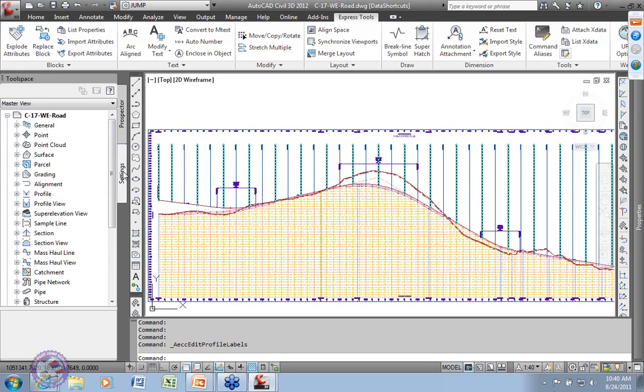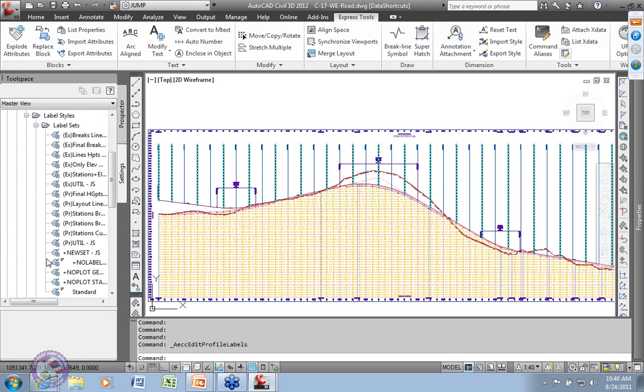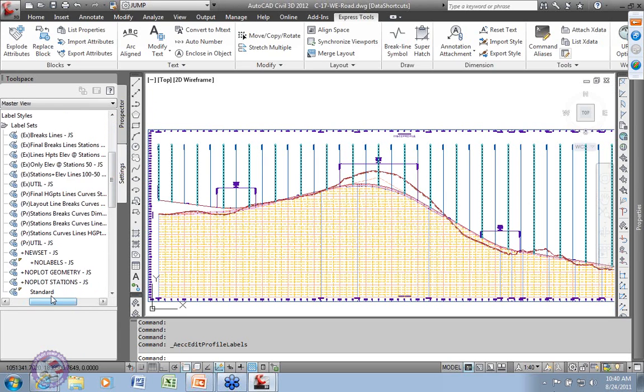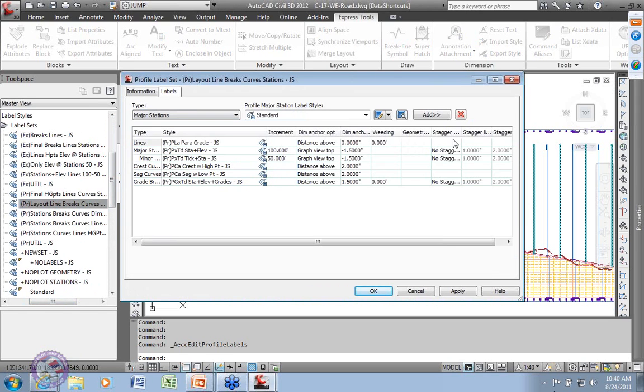if I edit the applied set, the set remains the same. So over here in settings, if I have a profile, label style, label set, these are where they come from. Here's what layout is. If I edit this and change what these parameters are and how stuff is done, which varies by that type of label and in part the style, how all that is done, that does not change this. So this is setting up your classic way you want to work.